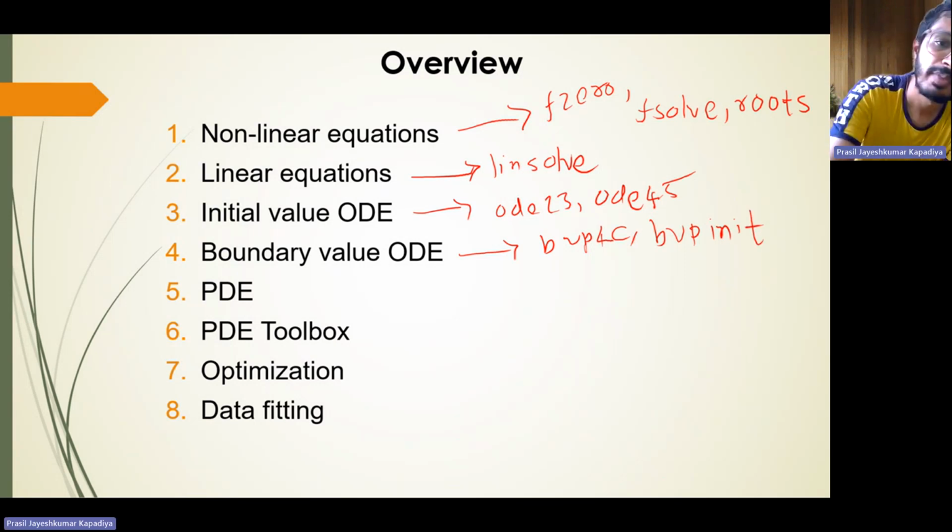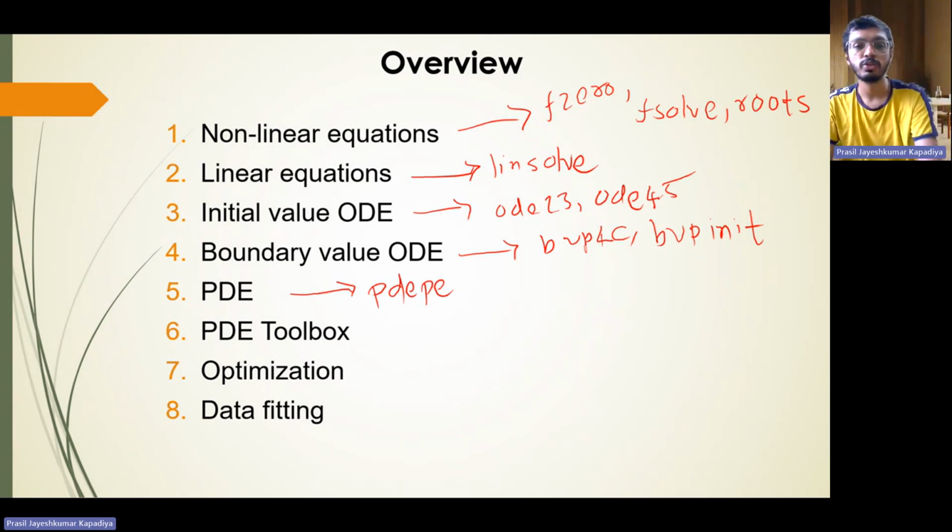Further, we solved partial differential equations, and there we learned pdepe, MATLAB inbuilt tool to solve these partial differential equations. We further used the PDE Toolbox, where we solved two kinds of heat transfer problems.